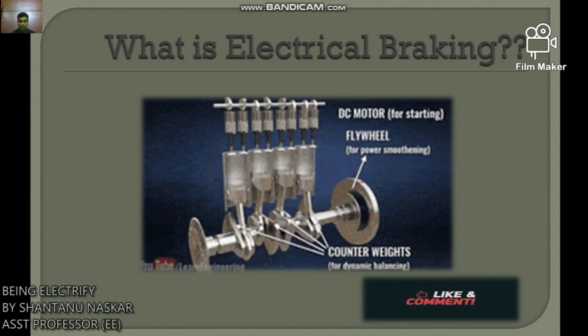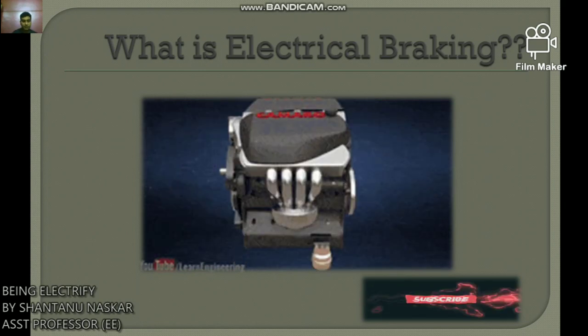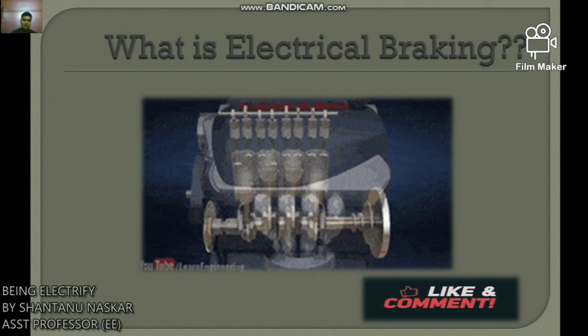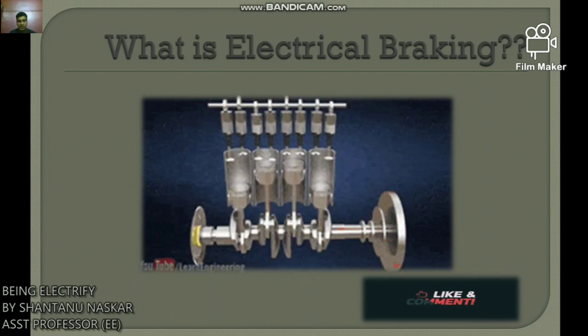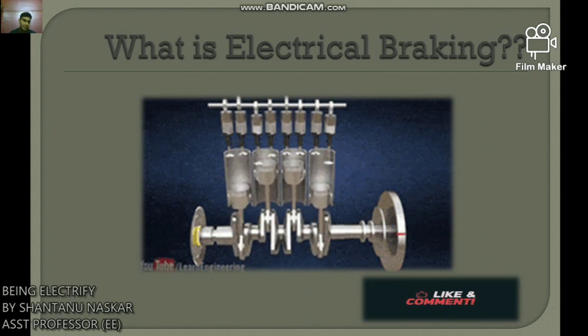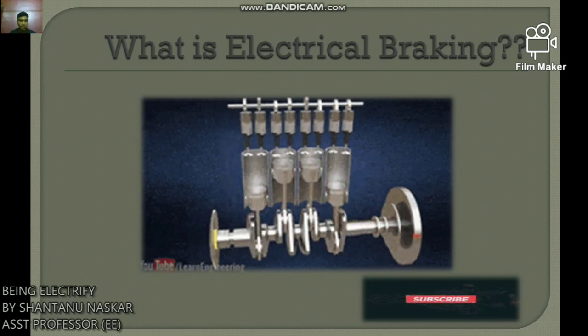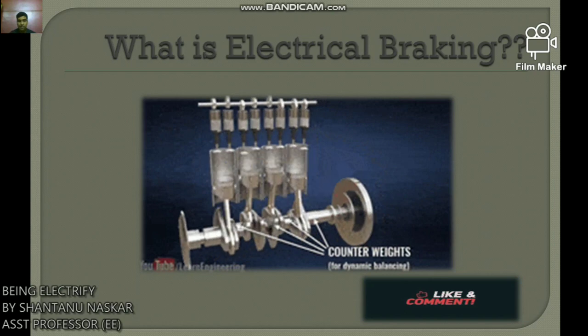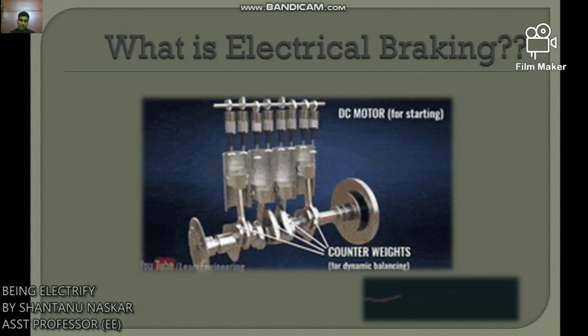Electrical braking allows smooth stops without any inconvenience to passengers. When a loaded hoist is lowered, electrical braking keeps the speed within safe limits. Otherwise, the machine or drive speed will reach a dangerous value.